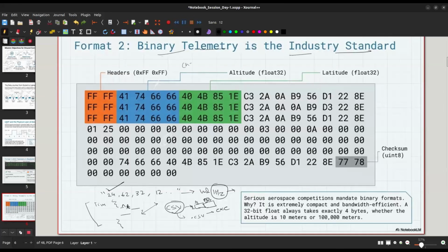Basically, instead of calculating the checksum, you can still calculate the checksum, but you can do this as well to ensure the data is consistent. It is not something that even your Zigbee is able to catch. There are times when your GCS is not capable enough to show that data. So what you have to do is create a header format, and after the header format, store your values like this. Let's say these are the four values fixed for altitude, two values fixed for latitude, for longitude, for temperature, for pressure. These are the values stored for different formats.